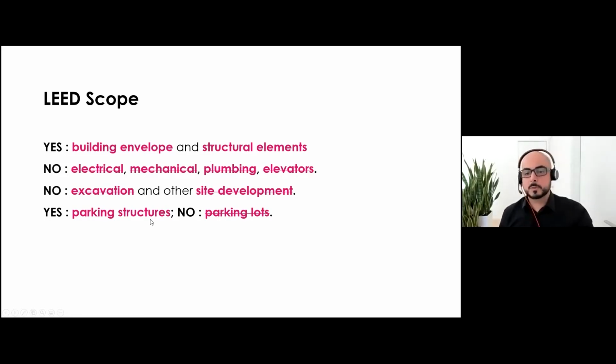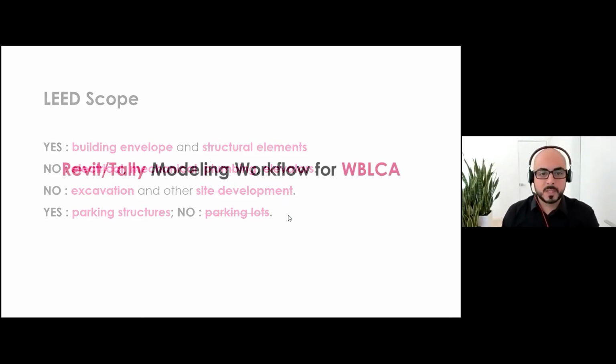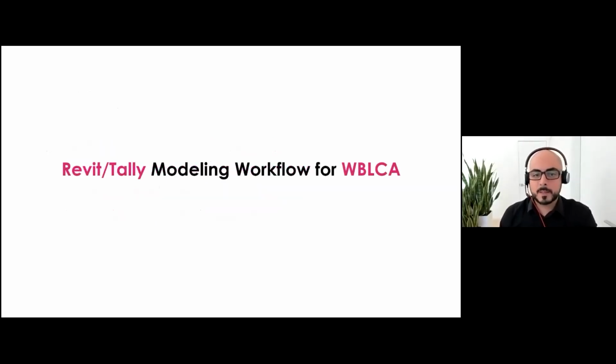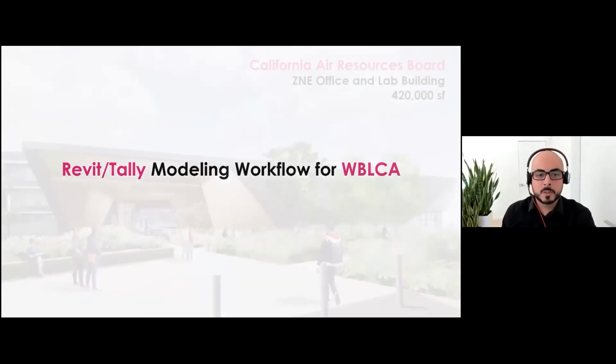So if you have parking under your building, you need to include it, but parking lots, you do not include. And then from a tools perspective, the workflow that we use is Revit and Tally. You could also use other tools, but your tool needs to be cradle to grave. So tools like Tally, Athena, One Click LCA would provide cradle to grave studies. EC3 is a cradle to gate tool right now, even though Tally and EC3 are merging now.